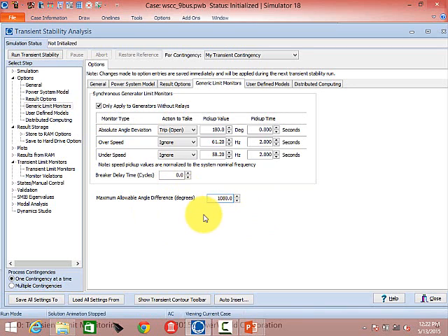Breaker delay time? As far as the default values, it would be interesting to know some basis for that, even if it's shaky. Most of the machines in the WEC dynamics file do not have under or over frequency protection in there. Do you know where those defaults came from that are in here, the 61.2 and the 58.2?